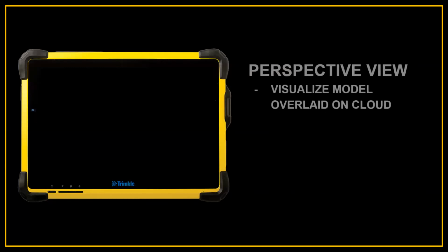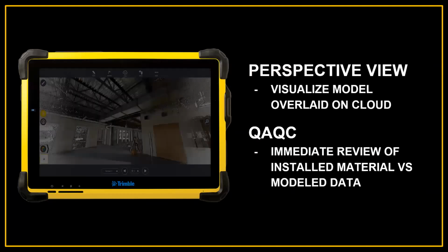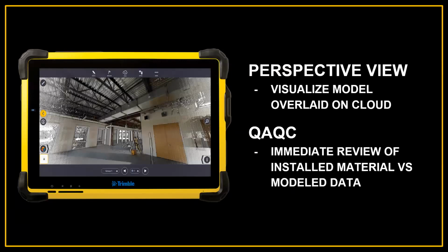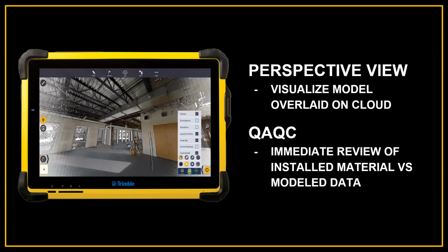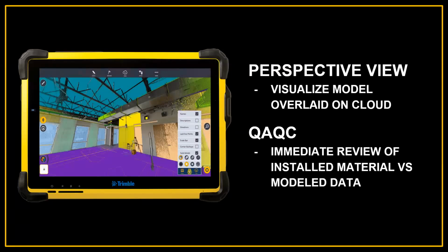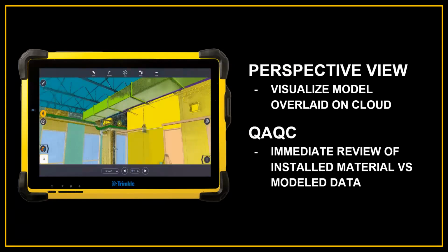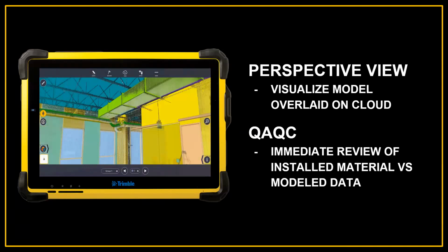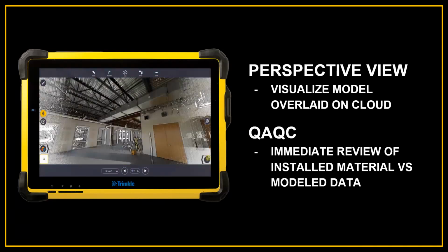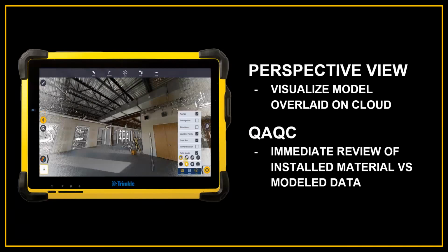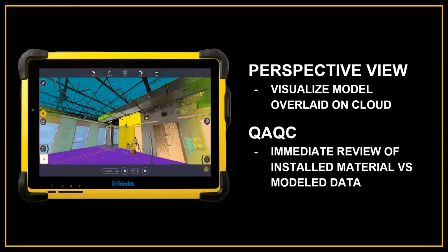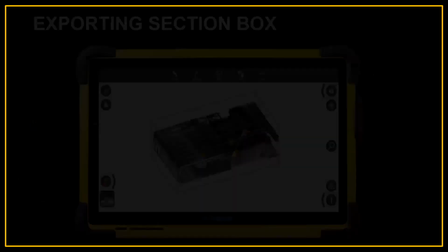Moving on from the station calculations, I can also have my perspective views. Now, when I say perspective, what I am doing is I'm overlaying. So this is something that Abhay was talking about a minute ago, when he was talking about bringing the point cloud and overlaying it on the model. Now, this is where I actually have my review of the design to the as-built, where I know that, okay, there was a particular duct going through here within my design. Is the duct constructed as per the design or not? I can overlay the design onto the point cloud. And these are my reviews that I do right there onto the model data. So you have your QA, QC done right in the field.